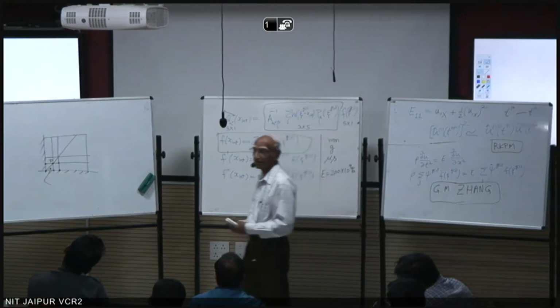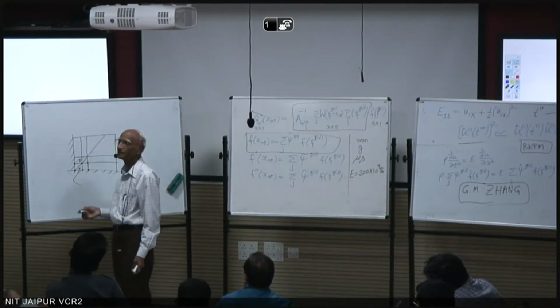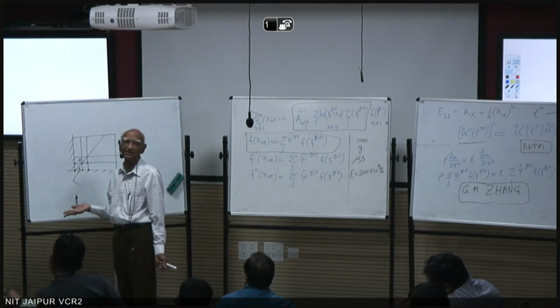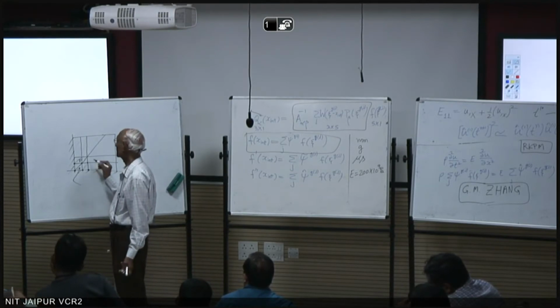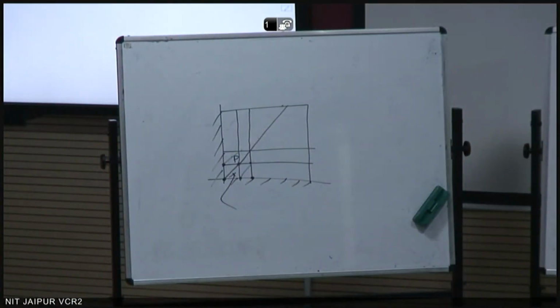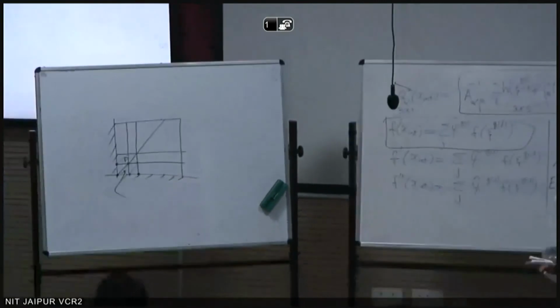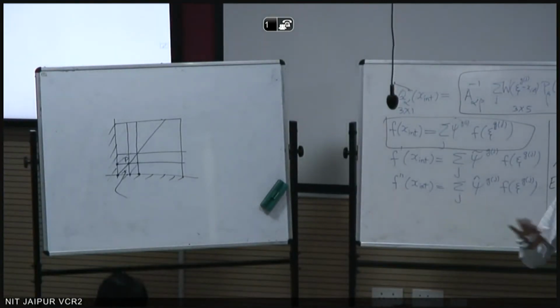So if this doesn't move anywhere, then you can go to this one, same argument. You can go to this one, same argument, same reasoning, right? So that means none of the nodes can move. Doesn't matter, because this is independent of the loading, right?